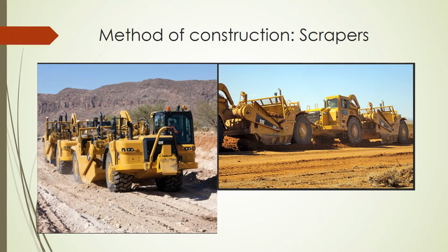So we now have the situation where we've got a successful design. We know the design is engineering correct. We've got some parameters. With regards to methods of building, the way we can build things is, first up, with scrapers. Now, scrapers are kind of self-contained dig, transport, dump machines. They're quite versatile in a lot of respects. They're quite quick. They really can power down slopes and excavate quite rapidly, but they do require highly skilled